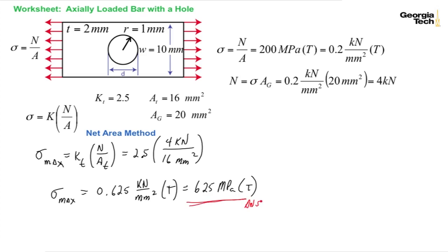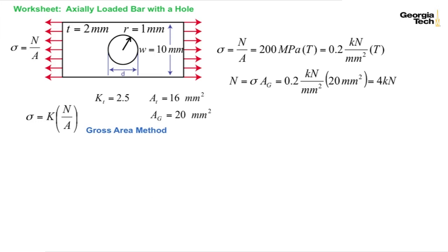Let's show that the maximum stress is the same using the gross area method. With the gross area method, I have to convert my K sub T for the net area method to the K sub G, the stress concentration for the gross area.